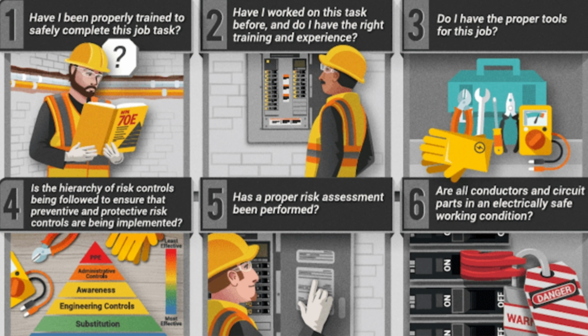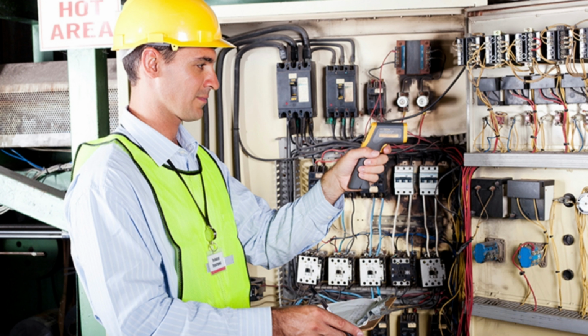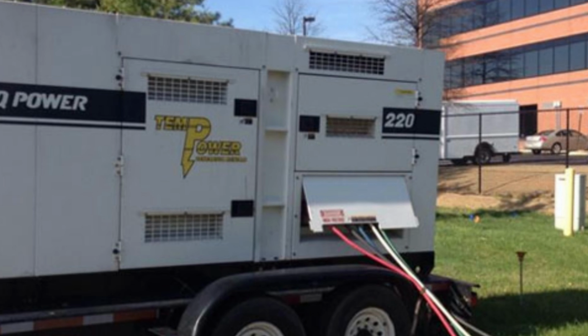The various protective systems available, such as fuses, earthing, low voltage, for example 110 V, and residual current devices, are used. User checks, formal visual inspections and combined inspection and testing are carried out on portable electrical equipment, as appropriate. In particular, temporary electrical distribution systems on site should be designed and installed by a competent electrician and protected from physical damage by suitable positioning, use of conduits and armored cable.